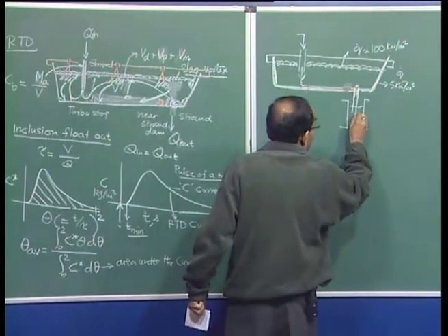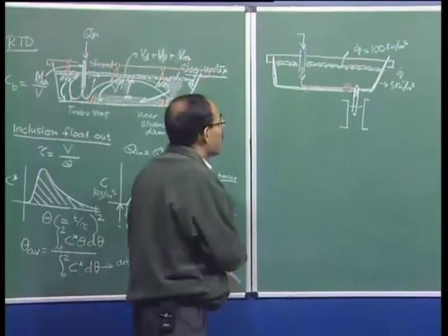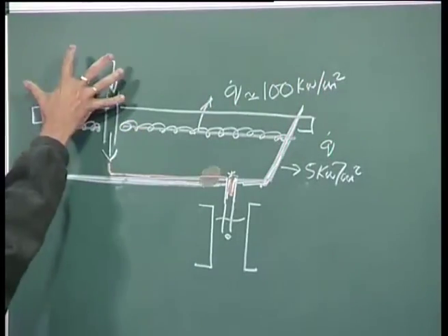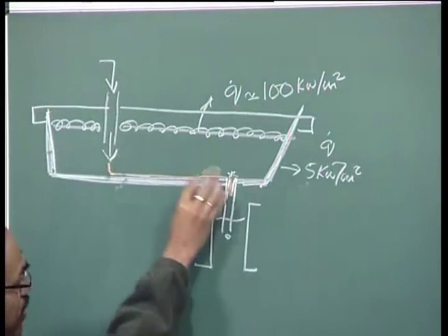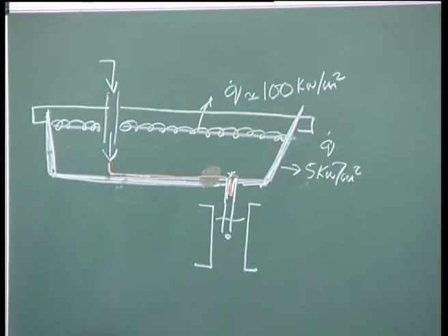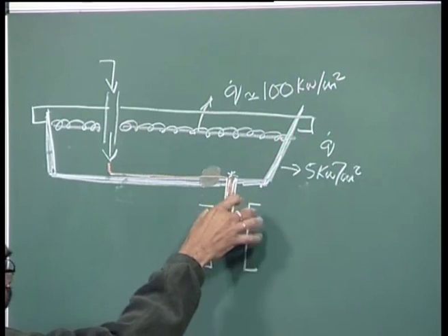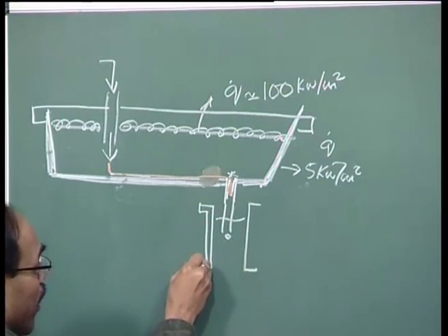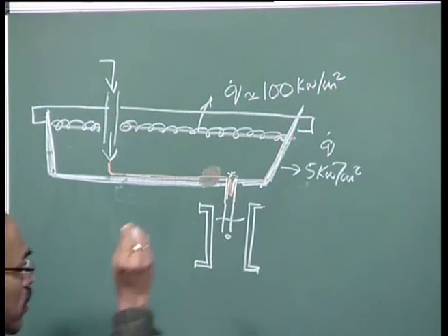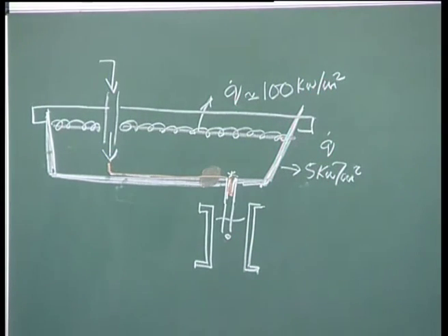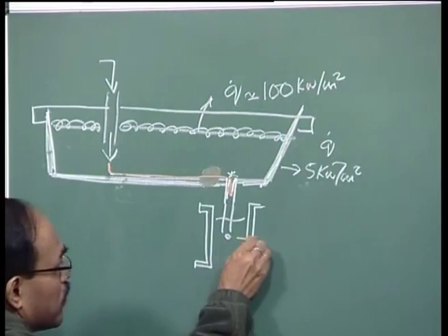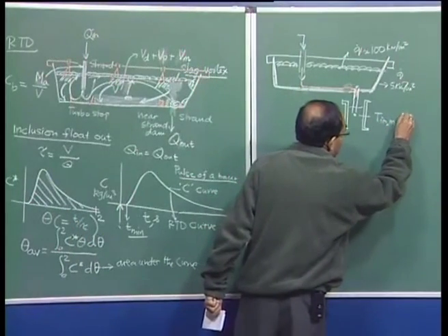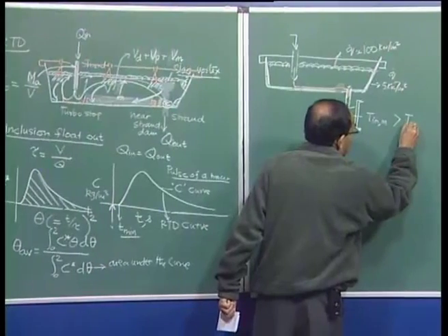So, here we can have relatively high temperature, because to compensate for this heat loss, we have arbitrarily increased the temperature by 20 or 15 degrees, and as a result material entering the tundish, entering the mold, this is the continuous casting mold. So, material entering the mold may now have a somewhat larger temperature. So, here T inlet mold is actually more than T desirable.